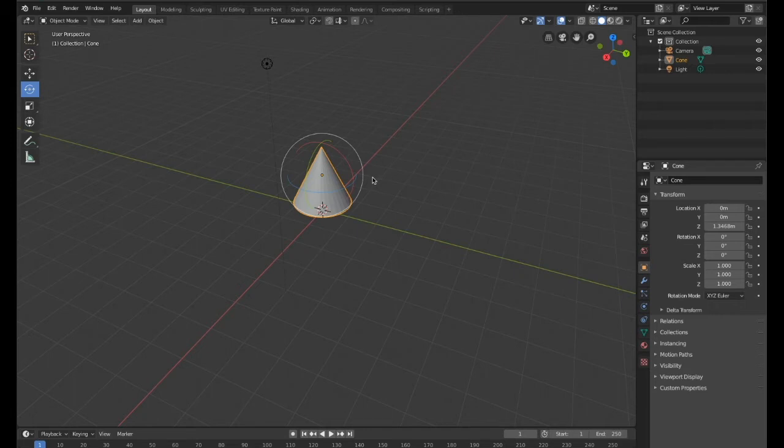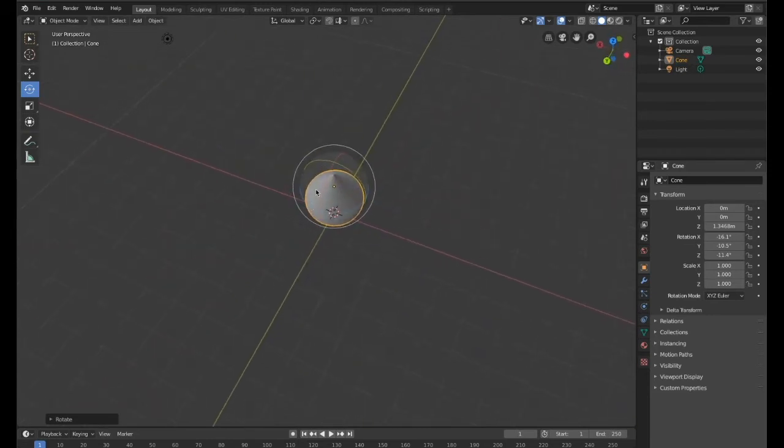Honestly, I think that I am going to rotate my object not by just eyeballing it, but I'm going to go ahead and go over to my contextual window. So there's a bunch of tabs here, and in this case, this contextual window lets me know where my object's located, its rotation, and its scale. So if I want to make my object larger on the XYZ axis, I could put that in here. But here I'm interested in rotating on the Y-axis. I'm going to make it 180 degrees.